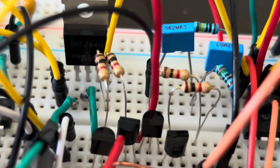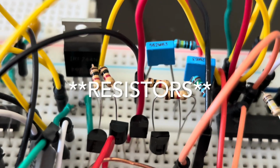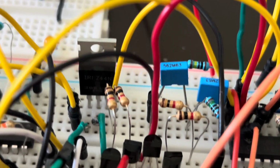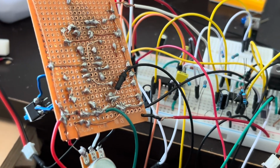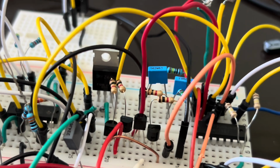The bases of the transistors are getting signals from these 1K potentiometers. Instead of going to ground, it's going to the MOSFET there in the background. And that MOSFET is getting its gating signal from the previously built PWM generator, and the output is going to ground.